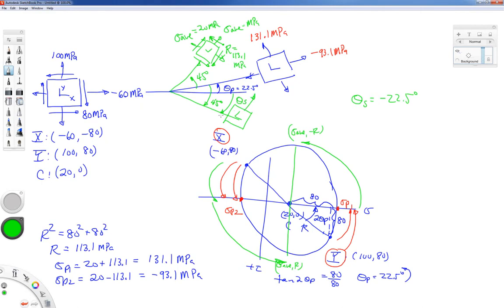Well, I know in this stress state, again, it's representing the maximum shearing stress state, I have sigma average all the way around. But in this case, I would have gone first from my original y and x diameter to the principal stress, and then backed it up. I would not have changed the sign of my shearing stress. It stays negative, so it really goes in this direction.